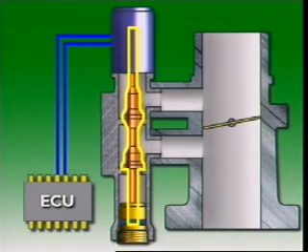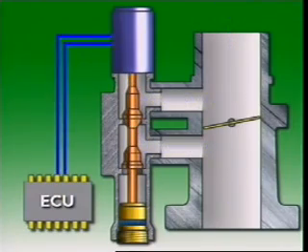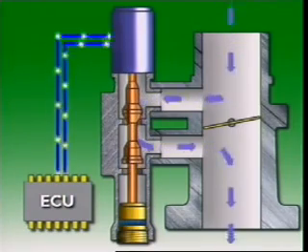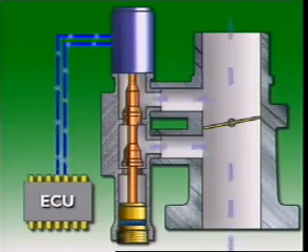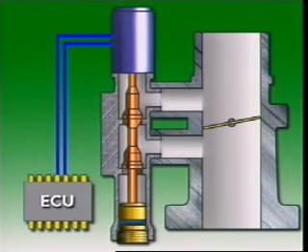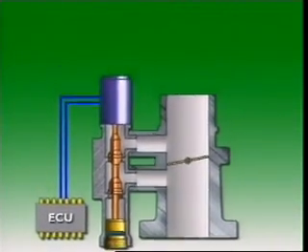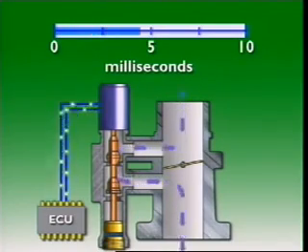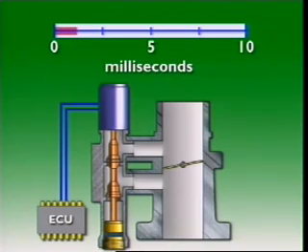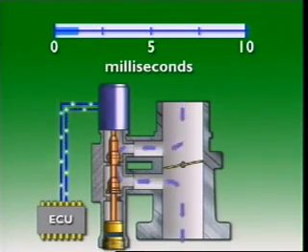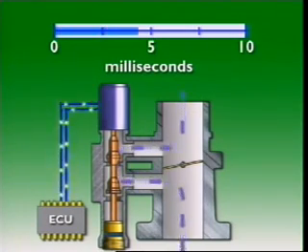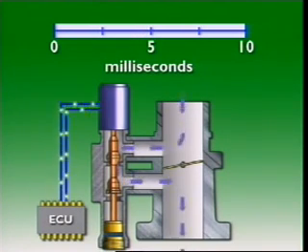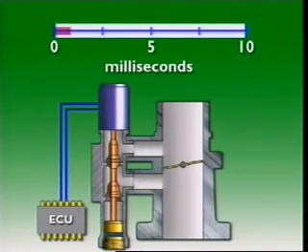Thereafter, the taper valve is positioned by pulsing the solenoid winding circuit at a predetermined frequency. The amount of valve opening, and therefore the amount of airflow, depends on the on time of the pulse. A long on pulse with a short off pulse will produce a high average voltage, and therefore a large opening of the valve. A short on pulse with a long off pulse will produce a low average voltage and a small valve opening.